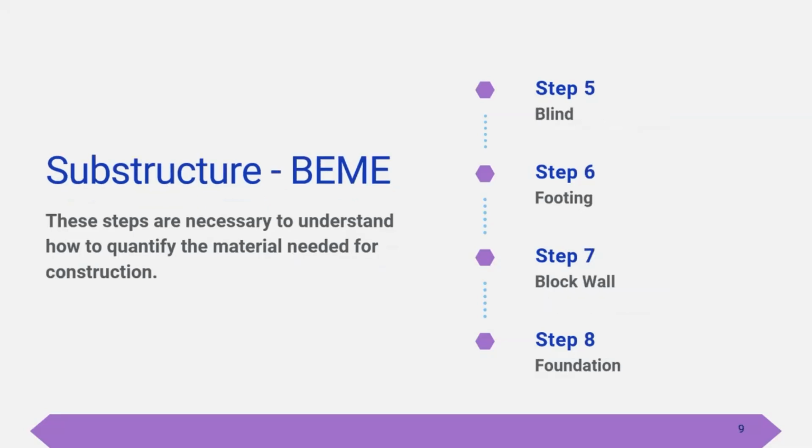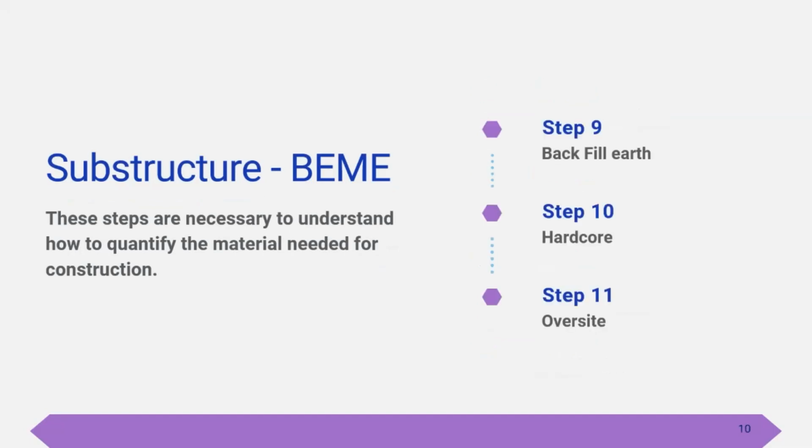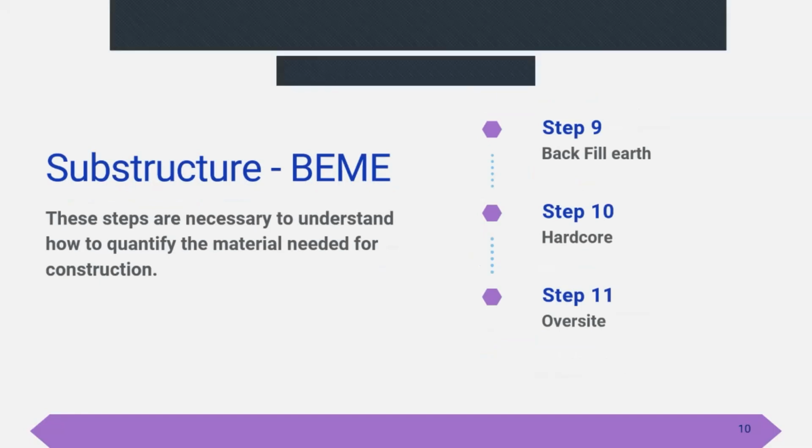Then the next is you blind it. After you blind it, you place your footing on it. Then after placing your footing, you place your block wall, because your block wall is what is going to bring it out before you have the opportunity to say, okay, this is where my foundation is. Then you backfill. Some of us witnessed when we were doing construction, right? You realize that after they do whatever they want to do beneath the soil, they use block wall to bring the appearance up to the surface. Then the next thing they do is backfill, because the block wall has helped you see, okay, this is the area I'm working with, but nobody will know what happened before now.